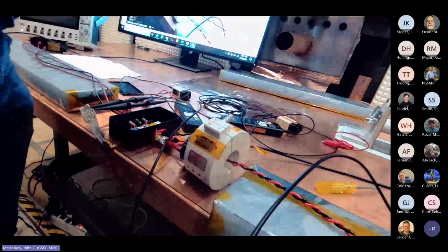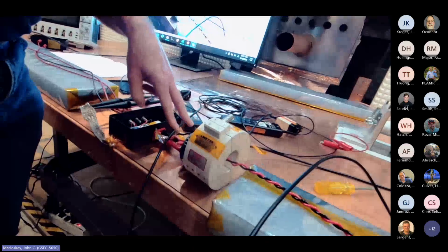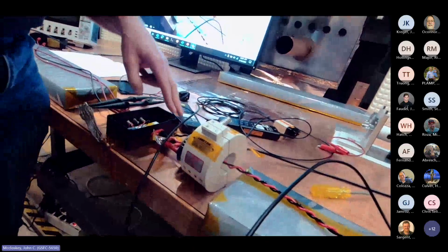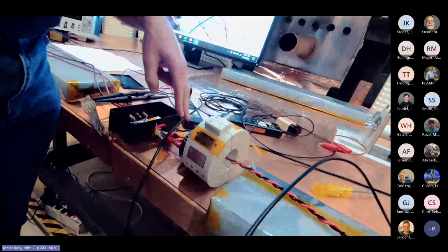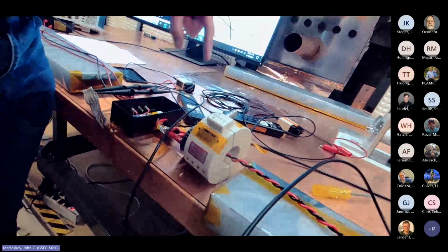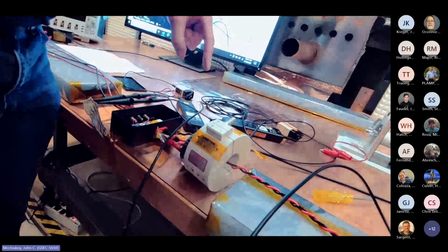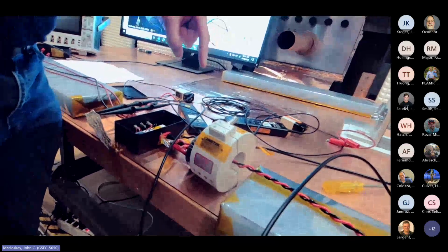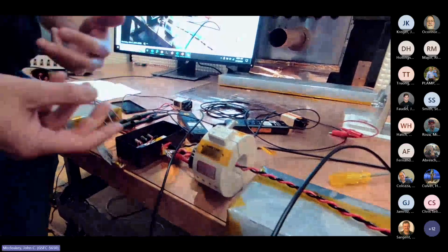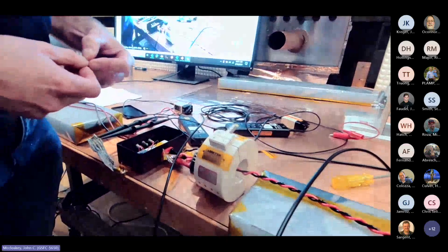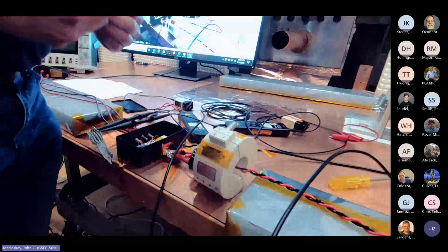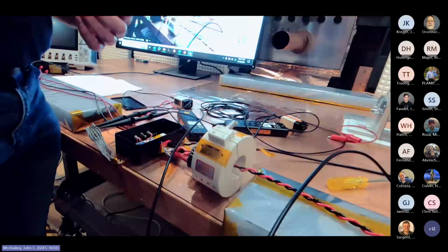In fact, at low frequencies with no shield, our test cables for power are generally unshielded for EMI. So with no shield at low frequencies, it should be a high impedance. So we shouldn't, and we won't get much current at low frequencies. But as frequency goes up, other paths, capacitive paths and stuff come into play, and you will get some more current. But the behavior of the current is going to be frequency dependent.